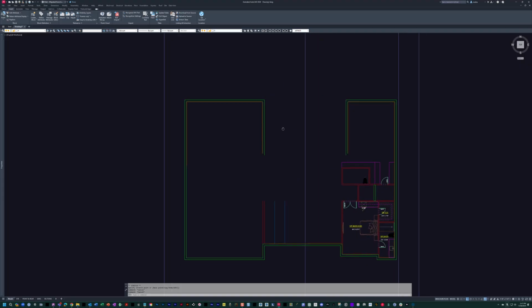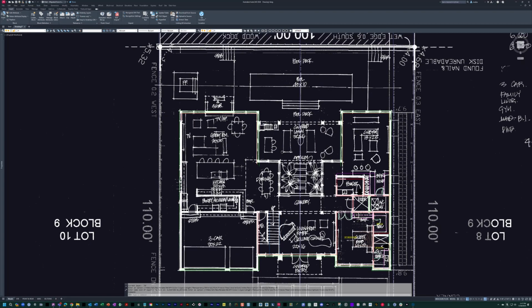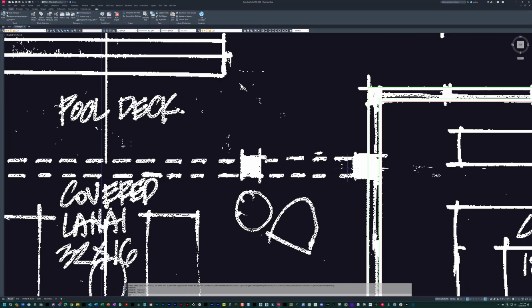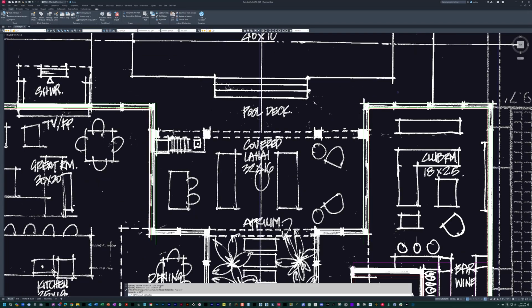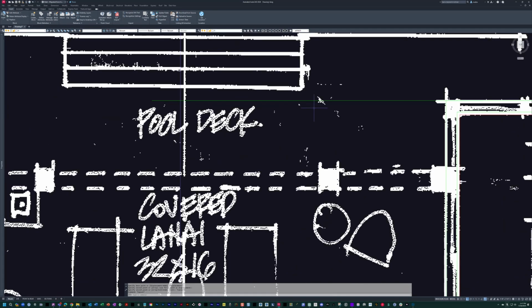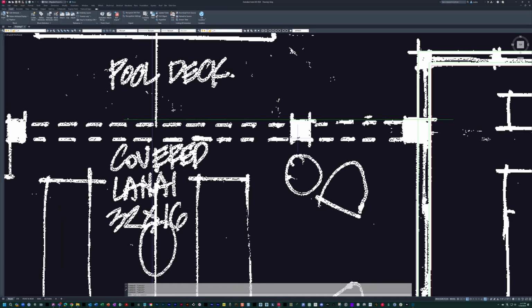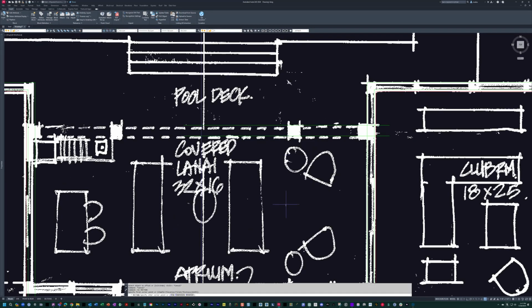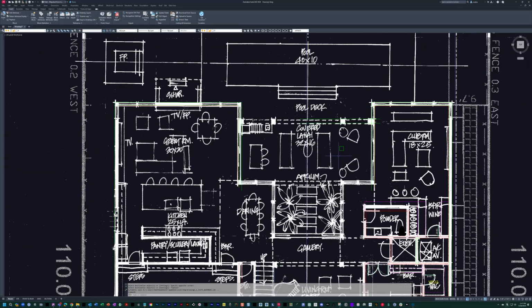So now we can quickly draw this atrium area. If we do a dimension down here, it looks like it's about 4-ish feet off. So that's good. I'm just going to pull a line over for reference, 48. And I know that this square, we usually do like to do at least 12-inch columns. So I'm going to offset 12 inches. And in fact, I'm going to go 12, comma 12, and create a block column for reference.